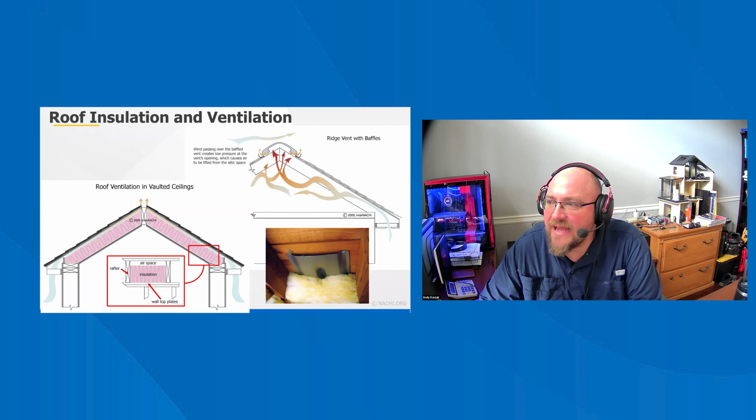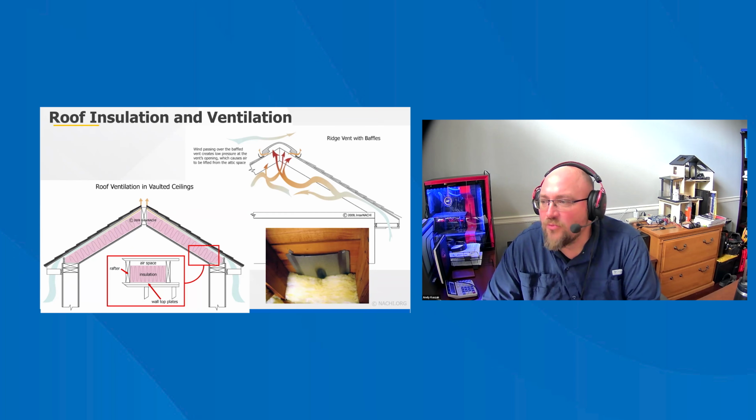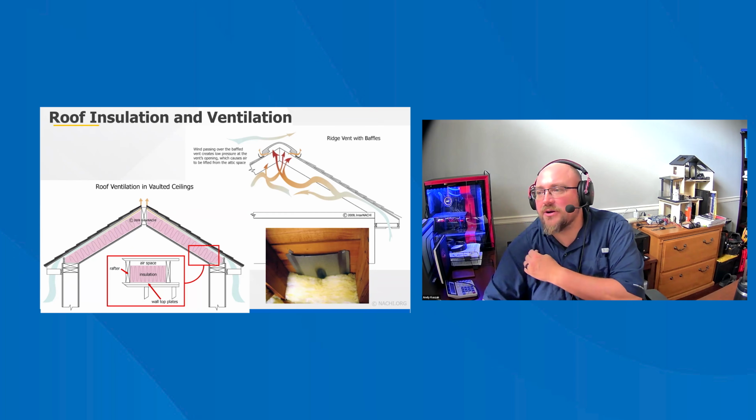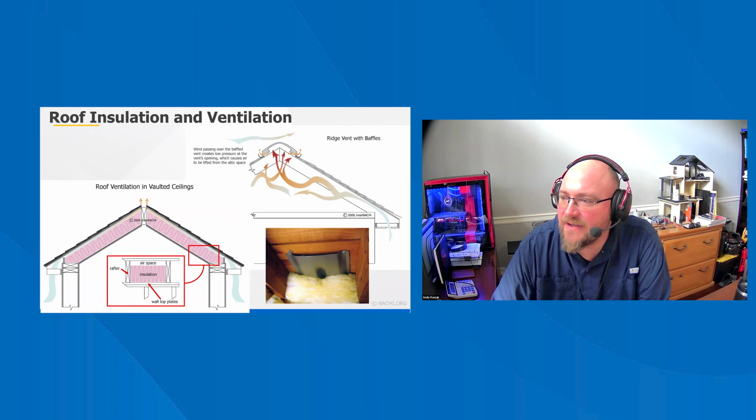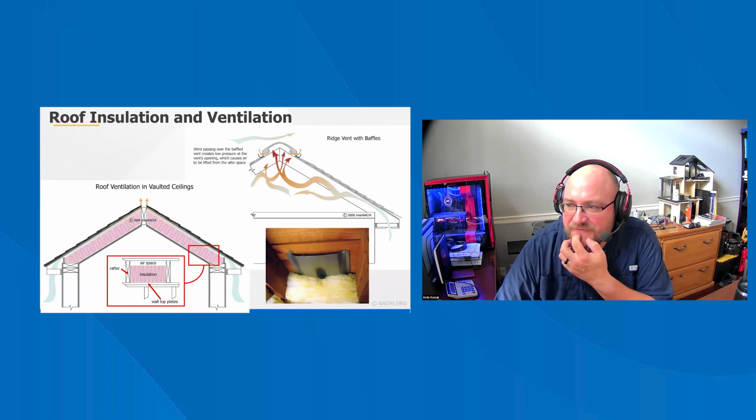To completely cover an attic floor with insulation out to the eaves, the installation of rafter vents, also known as insulation baffles, is needed. Complete coverage of the attic floor, along with sealing any air leaks, will ensure the homeowner gets the best performance from the insulation. Rafter vents ensure that the soffit vents are clear and there is a channel for outside air to move into the attic at the soffits and out through the gable or ridge vent.